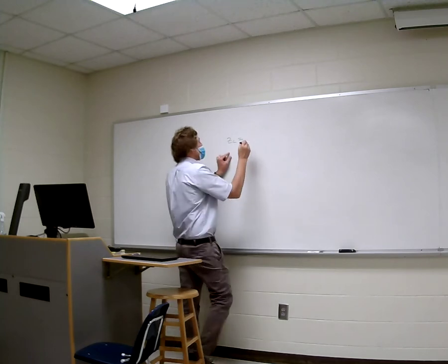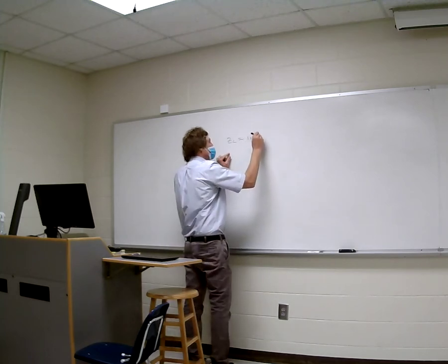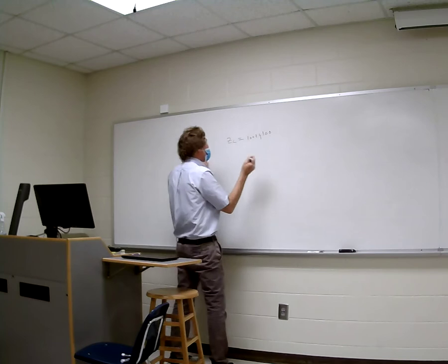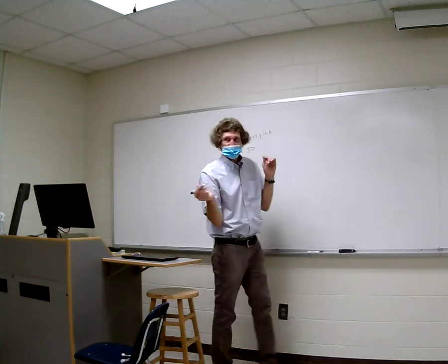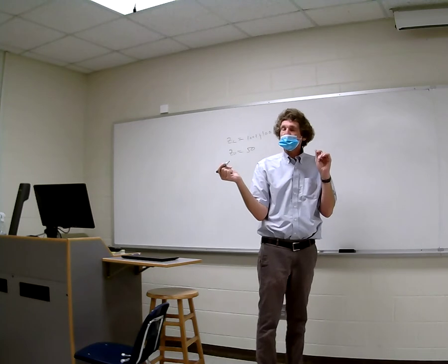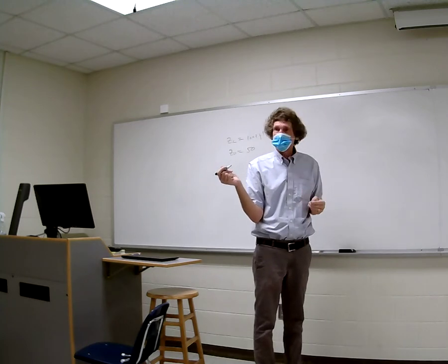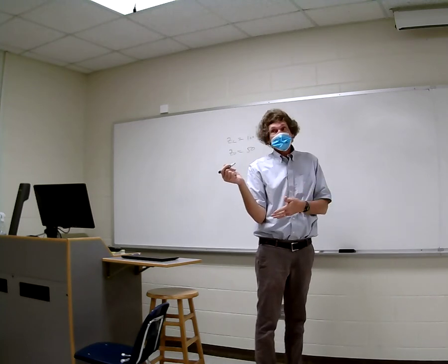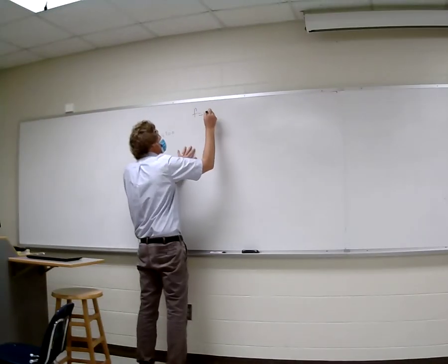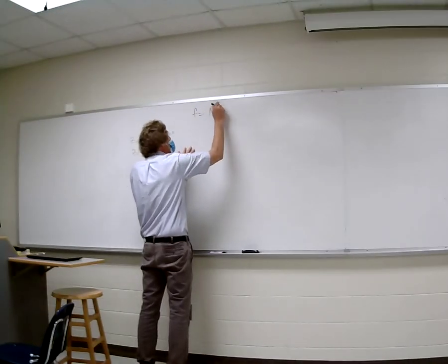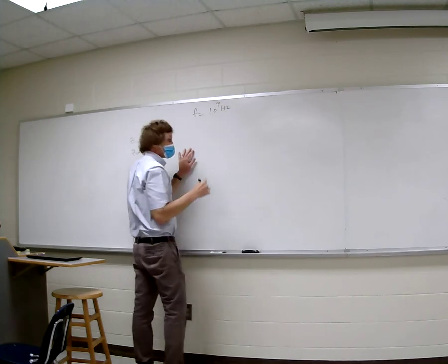All right, ZL is 100 plus what? j100. Okay, and Z naught is 50? Yes, sir. All right, and you want this matched, right? We want to develop an L-series matching network. Okay, now this is one of those things. Oh, you need the frequency. It's 1 giga, 10 to the 9th hertz, which is really nice.